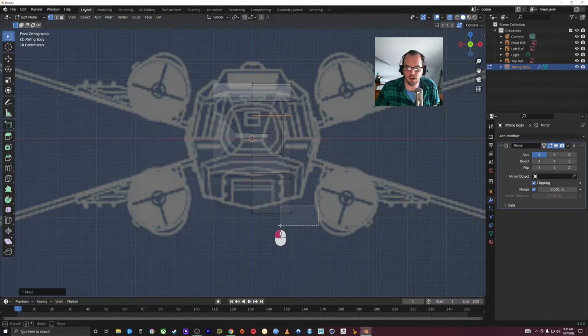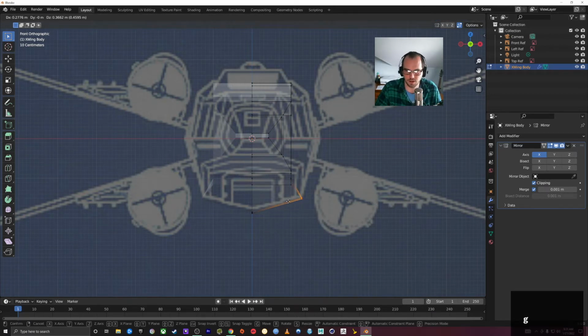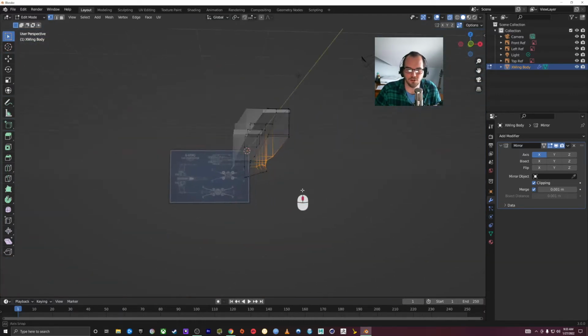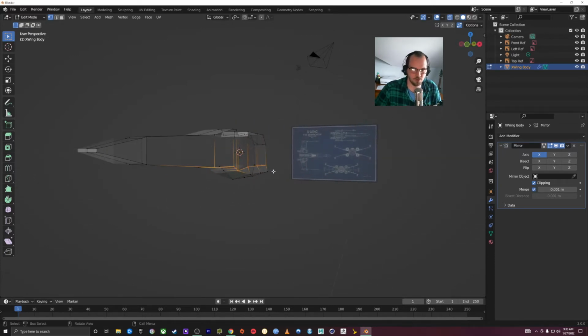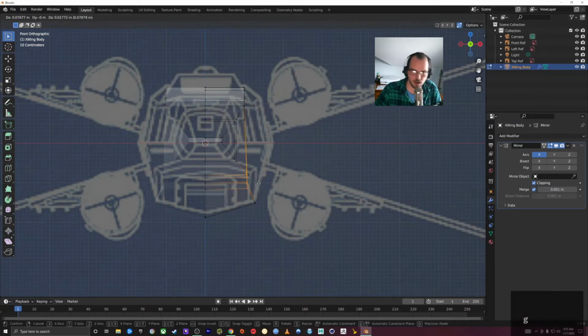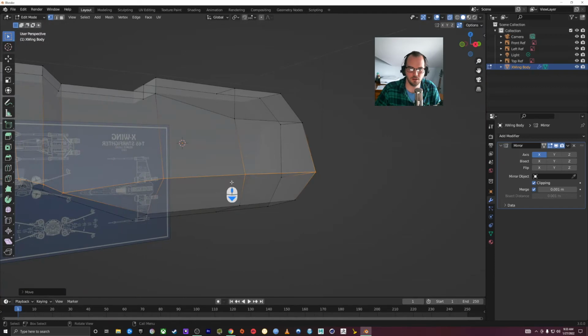So I'm going to attempt to form this shape in a little bit nicer way. I'm going to grab these edges here. I'm going to hit G. I'm going to put them right here. And obviously you can see that from the front view, we have lots of different vertices that are not lined up. So looking back here, those are the ones on the very bottom. You're going to be switching between your views quite a bit. So this was the hull and the back. These ones here that I'm selecting are like the outer part of the front, which we went to about here, maybe.